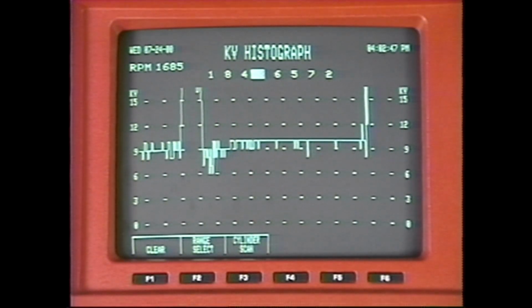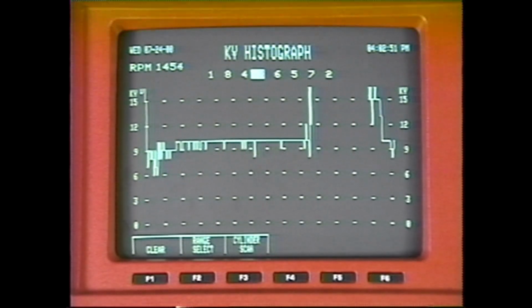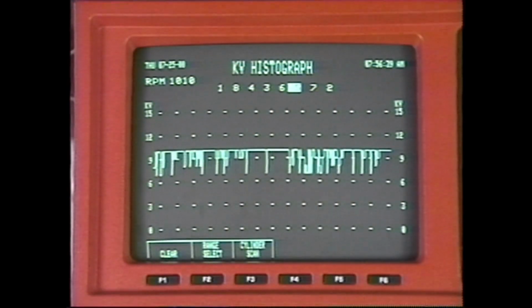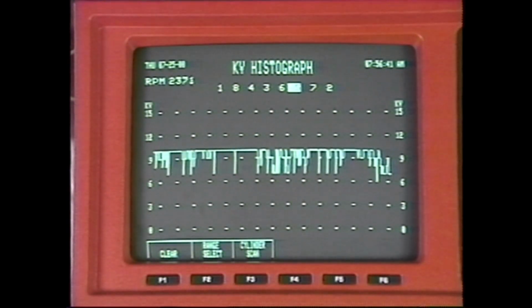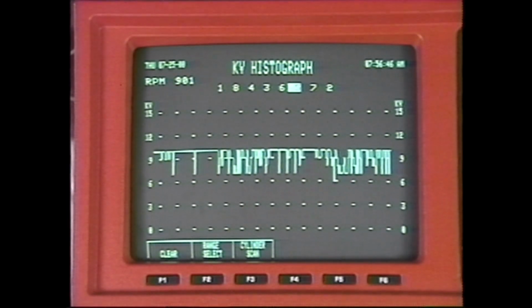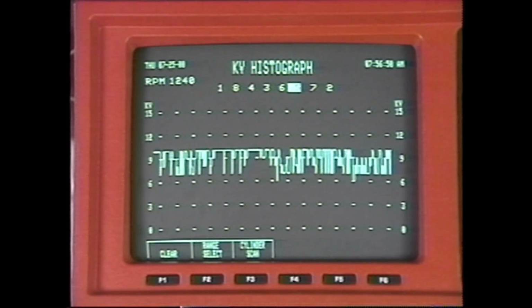If the firing voltage increases dramatically when the throttle is open, the problem is in the internal combustion chamber. It may be a fuel problem. If the firing voltage is low during the no-load test and stays low during the snap acceleration test, the secondary resistance is very low.